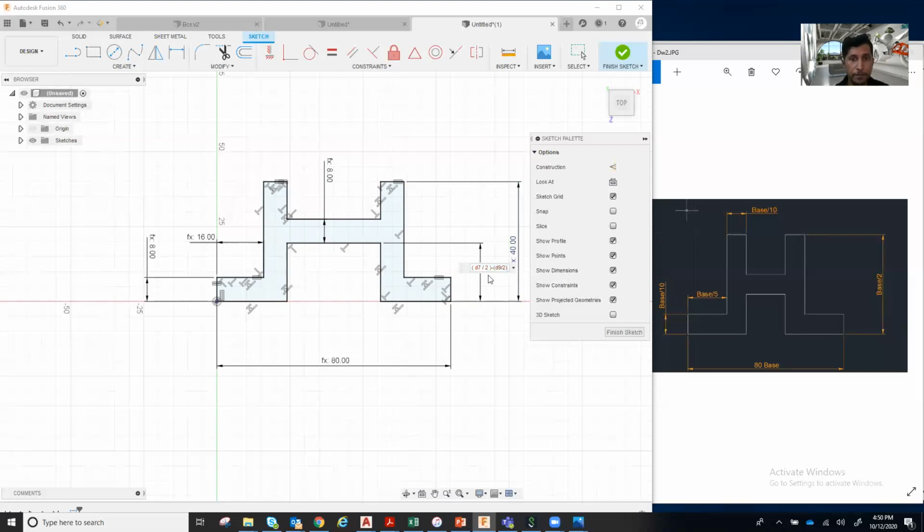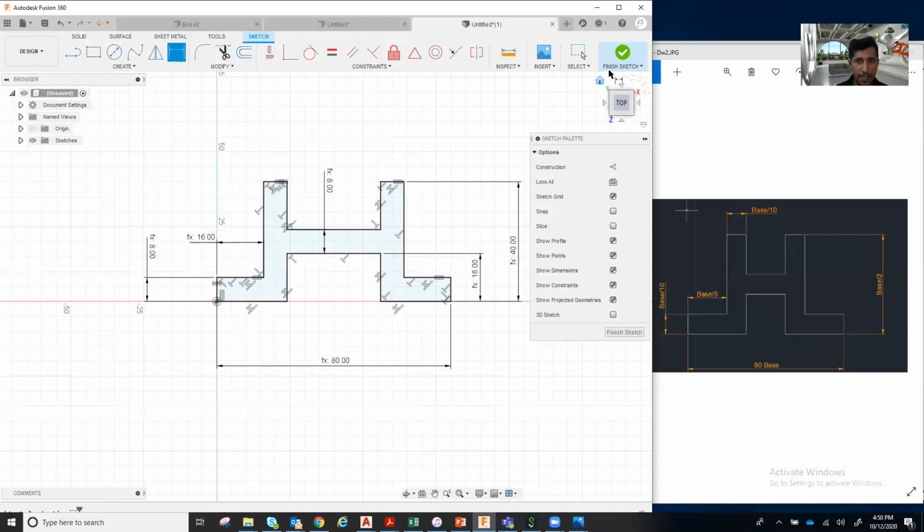Am I right? So this length is nothing but total height divided by 2, that is the center. So it has to go down. So total height divided by 2 minus thickness divided by 2. So once I enter, I can give a formula like anything, I can add to this formula. So after adding the formula, now I go to stop sketch, the same procedure, I stop the sketch here. Okay.